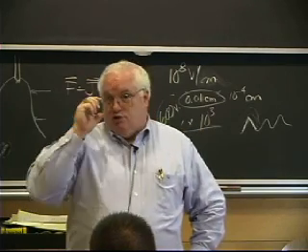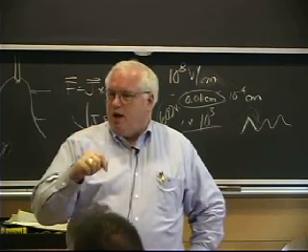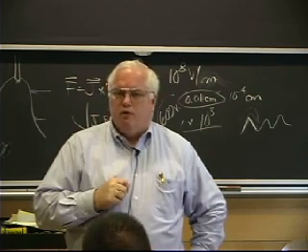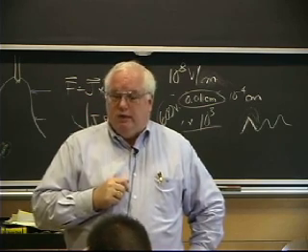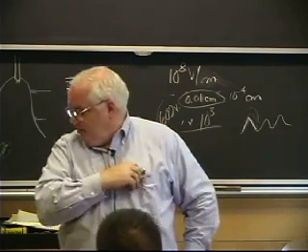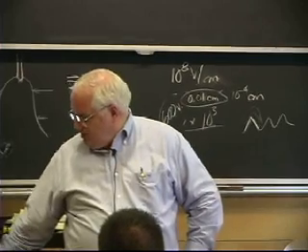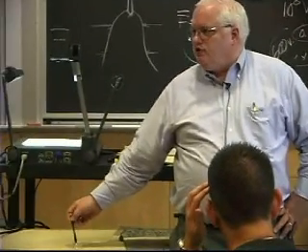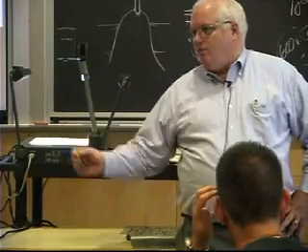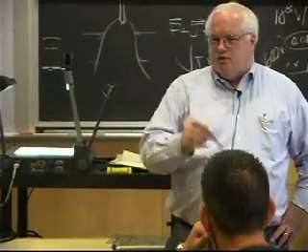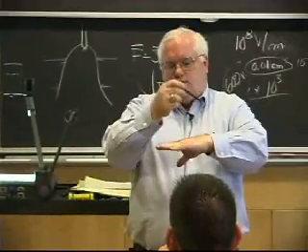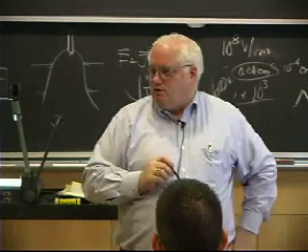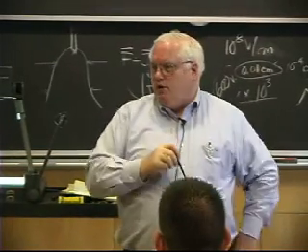We use the last two, touch starting and high frequency, to start electric arcs, and it's important for robots because robots don't have the manual dexterity to come in and make a nice, soft touch. They kind of come in and bang, right? They don't know exactly where the material is. Ordinarily, a real welder comes in at an angle like this and kind of scratches it across the surface. But robots would hit it too hard.